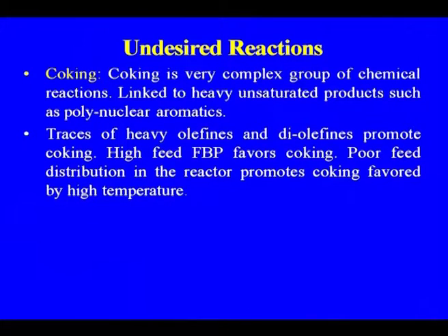So, traces of heavy olefins and diolefins promote coking. High feed boiling point favors coking. Poor feed distribution in the reactor promotes coking, and coking is also favored by high temperature.